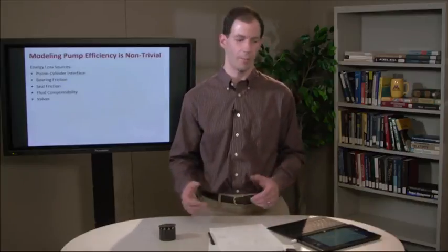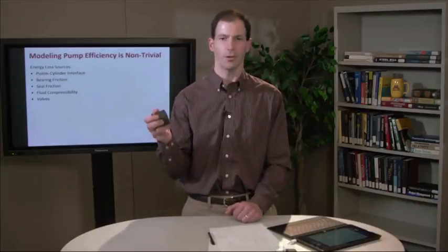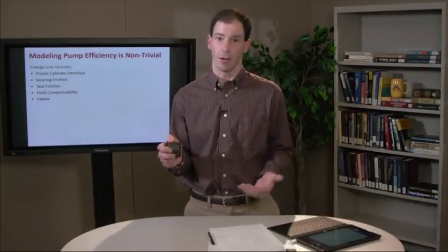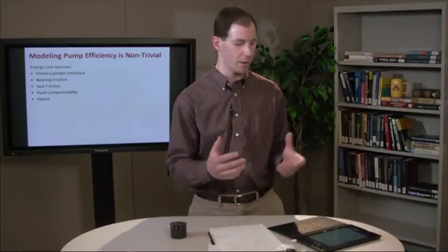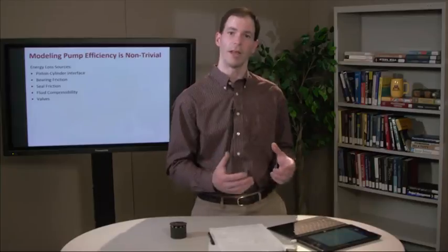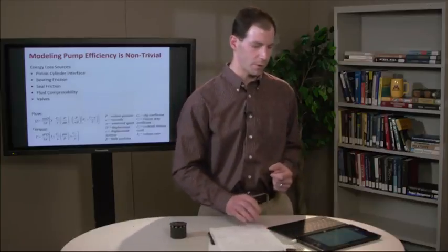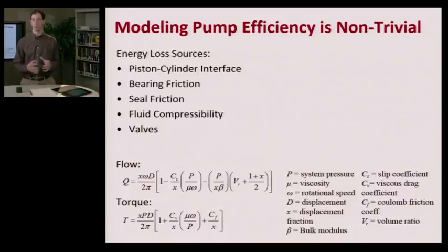Now, how do you do this for a pump that you might buy from a manufacturer? Now, you could try to model all these, but that means you have to disassemble it, you have to inspect everything. There's a lot of unknowns going on here. What more often happens to treat all of these energy losses is we say, I recognize I have all these losses. Now let me characterize these experimentally. So I'm going to run a large number of experiments and really develop a map of the efficiency as a function of perhaps the pressure, the speed, perhaps the volumetric displacement of the pump, and then take all of that and curve fit it. And these are some common equations that are used.